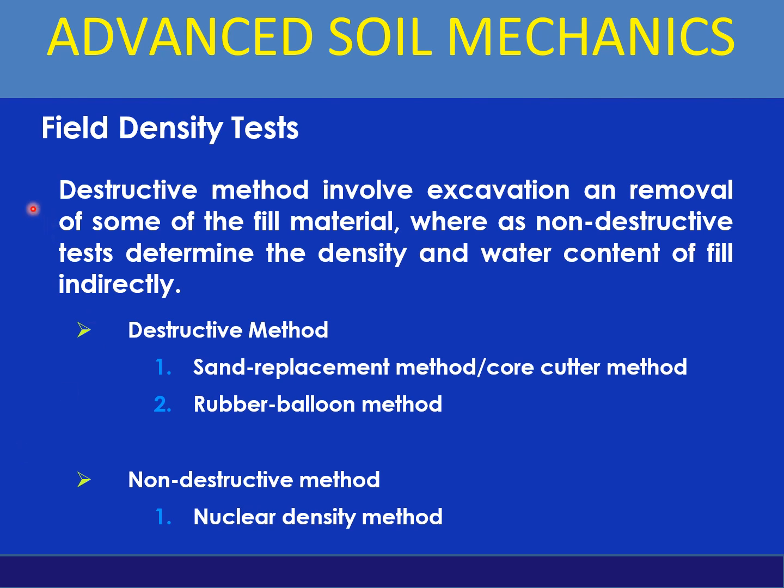Destructive methods involve excavation and removal of some of the fill material, whereas non-destructive tests determine the density and water content of fill indirectly. In destructive methods, we have the sand replacement method or core cutter method. These are the two methods that we use generally, or the rubber balloon method.